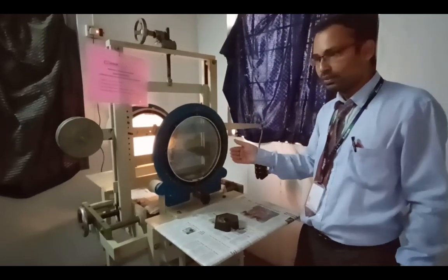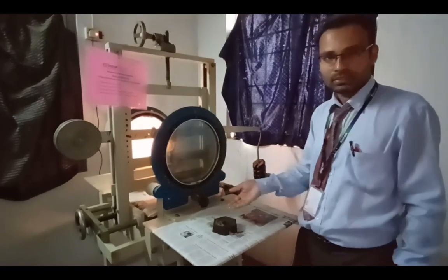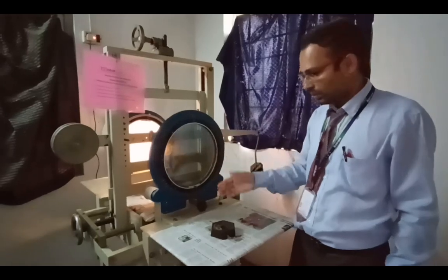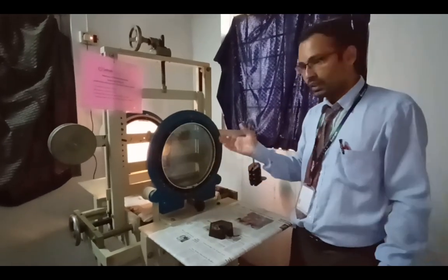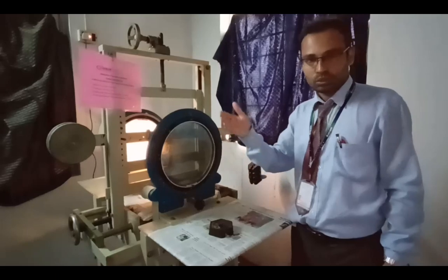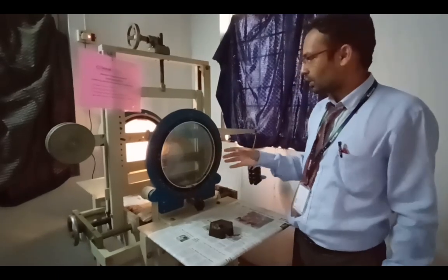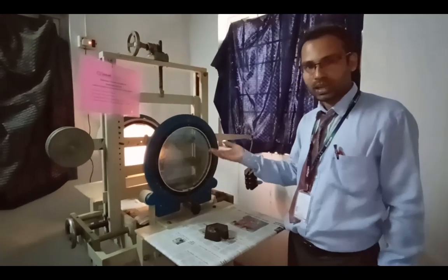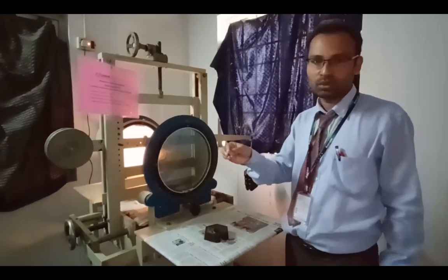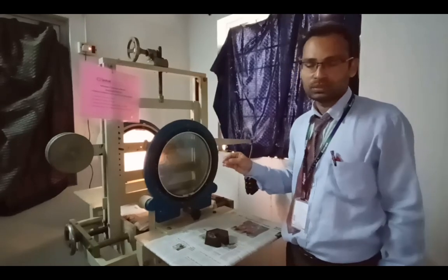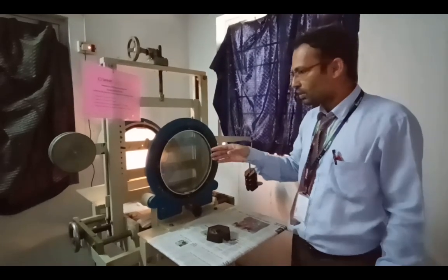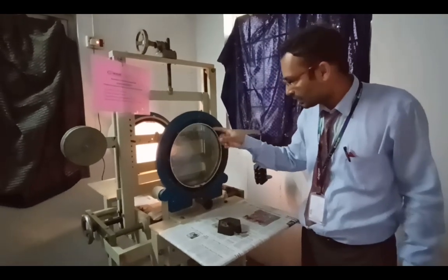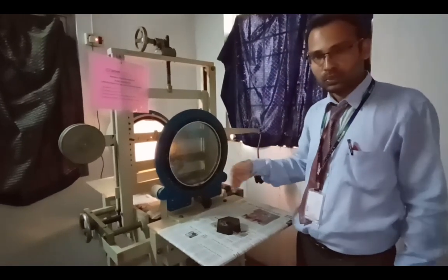The remaining part I am going to explain in the next session: how we calculate the principal stresses with the formula. We calculate the theoretical and practical values. Theoretically, you need to calculate the principal stress difference sigma 1 minus sigma 2 with the help of the formulas I gave in the tabular column. Then you compare, and you get the number of fringes. You also need to plot the load versus fringes graph and calculate the fringe material value from the graph. That also I will explain in the third part.